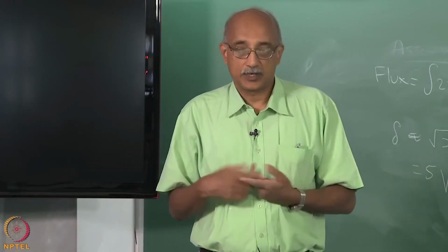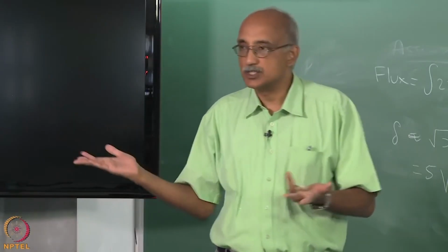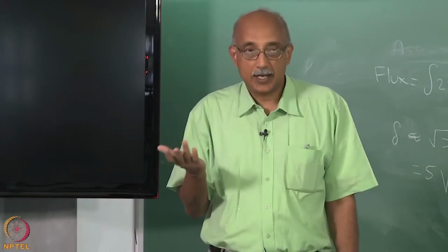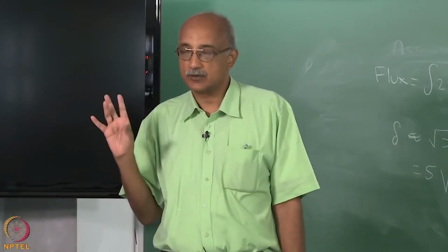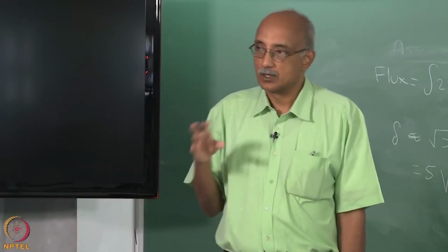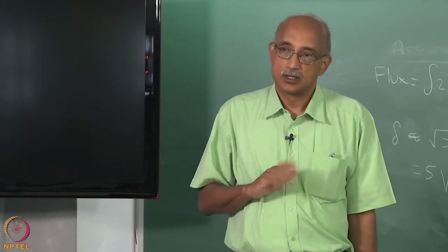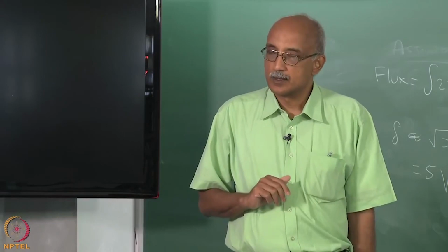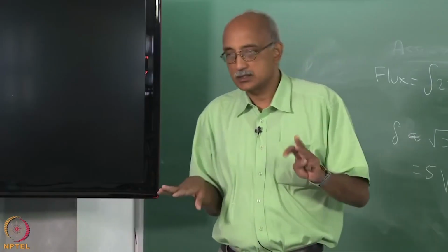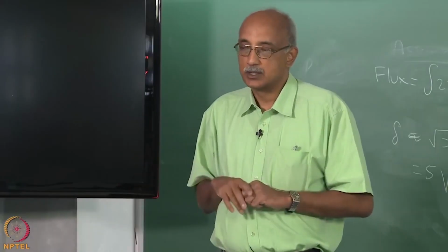And then for example, if silicon is what you are trying to deposit and silicon is distributed among 10 species, it will calculate the rate of deposition of each of these species, and from that it will calculate an effective deposition rate of silicon simply as a weighted sum of the deposition rates of all species containing the element silicon. That is a conventional approach. The problem with that approach is it may not be self consistent, because it is assuming that transport and the thermodynamic processes can be decoupled.